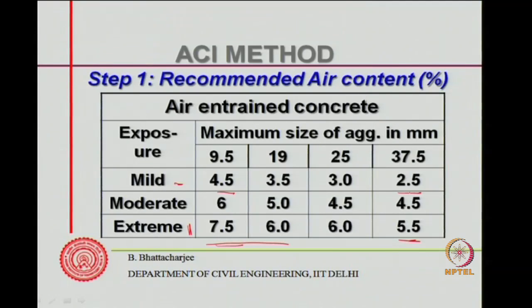So, your dosage of air entraining agent should be such that it gives you at least this recommended air content when it is exposed to extreme freeze thaw condition, mild, moderate and extreme situation as defined by the code. So, this is the air content.